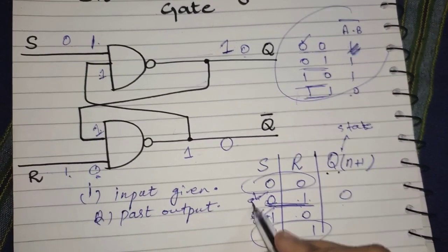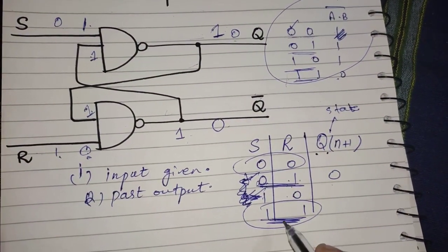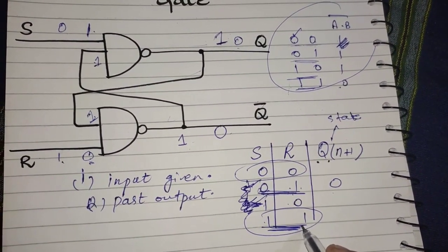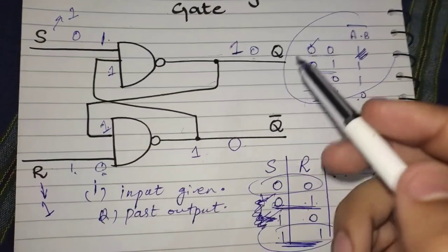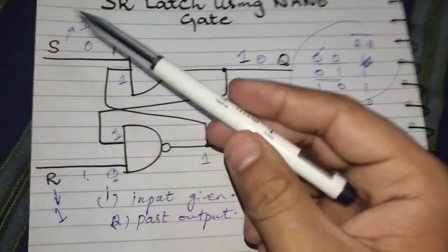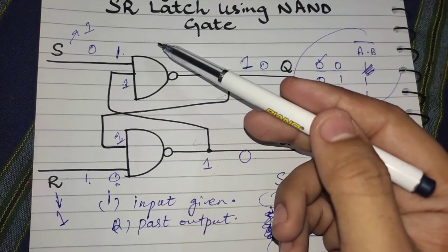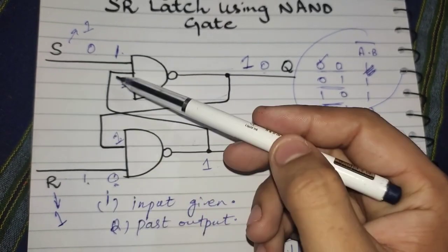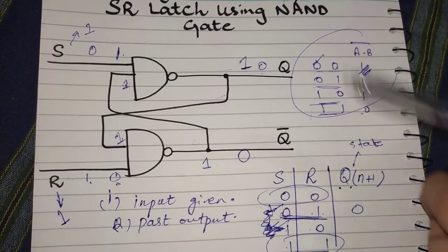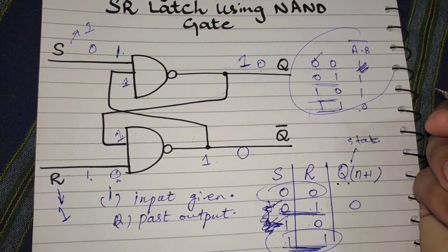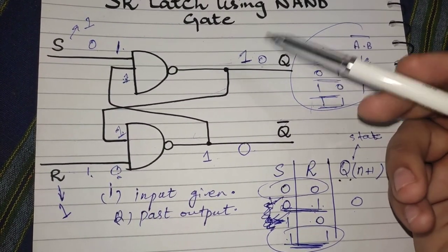So we have these two states which are easy to implement in the SR latch. Now come to the third point, which is when I am giving 1 and 1 as input to the system. Let's say I am giving 1 in S and 1 in R, what will be our output? It is difficult to say whether our second input will be 0 or 1. We have unknown second inputs, so we cannot recognize them. In that case, it is difficult for us to implement that SR latch.